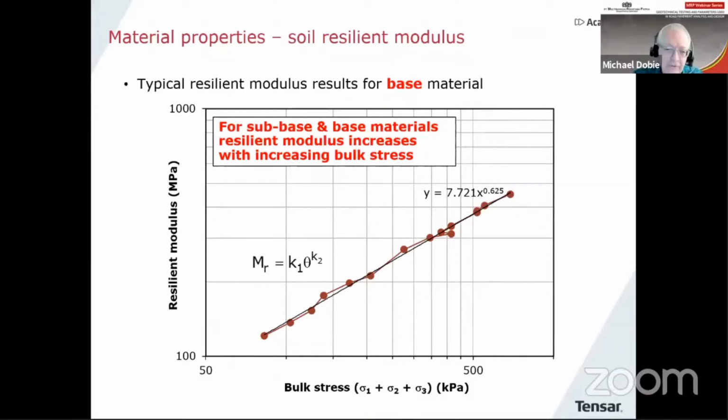If you look around for them, you can find that very often for all sorts of different materials, if you want to get some assessment of the resilient modulus of a material that you're using. Sadly, I don't think many laboratories do this testing. I don't know if in Indonesia there are any laboratories that can do resilient modulus testing of coarse materials, but luckily there's plenty of correlation around, and it's the correlations we often rely on to get these sorts of numbers.